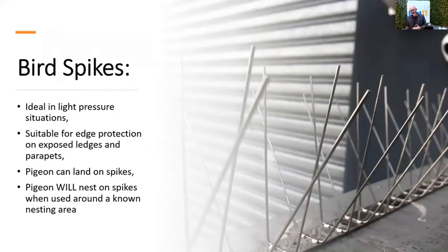Bird spikes, well, I've probably been a bit negative on bird spikes when it comes to pigeons, particularly when they're nesting, but in light pressure situations where you've got full exposed parapets or ledges, bird spikes can give you some edge protection to stop you from seeing the bird defecating over the front of a facade. But again, wherever there's any sort of protection over the top, I would be removing the use of bird spikes because there's that potential for birds such as pigeons to continue nesting.